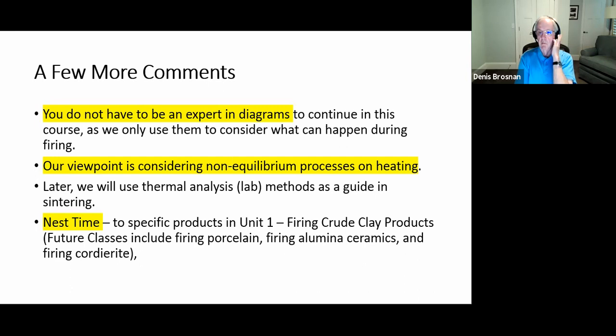Okay, but you need some liquids in firing to aid in sintering unless you're trying to work with a very high purity system where you don't want any liquid at all. Liquids are going to aid in sintering, and that's the bulk of all the tonnage of ceramics that are manufactured in the world using vitrification, sintering, or reactive sintering.